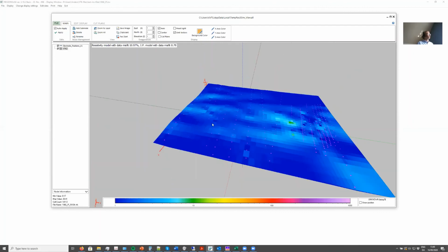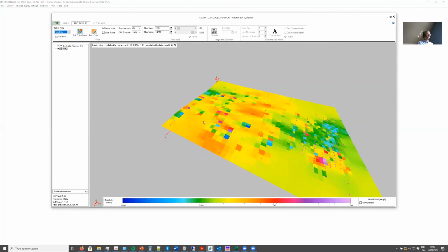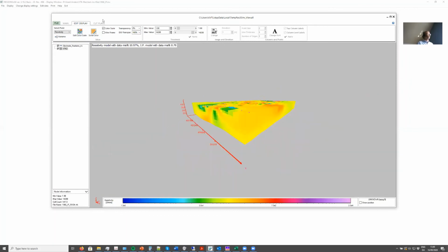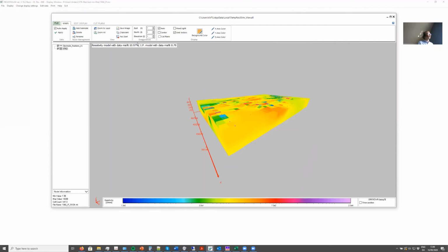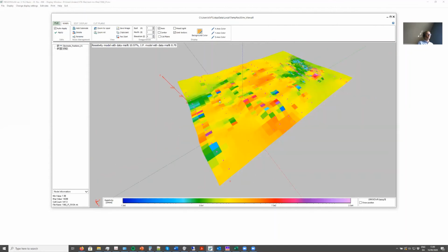And if I just switch to the resistivity view, you can do this under display, select field IP or resistivity, then it will look like this. And if you want to be able to see the topography more clearly, you can add a vertical exaggeration to the display. You do this in the main tab, where you can exaggerate in different directions. So I'll do it in the elevation direction in this case. You can see now you can really see the topography kick in.